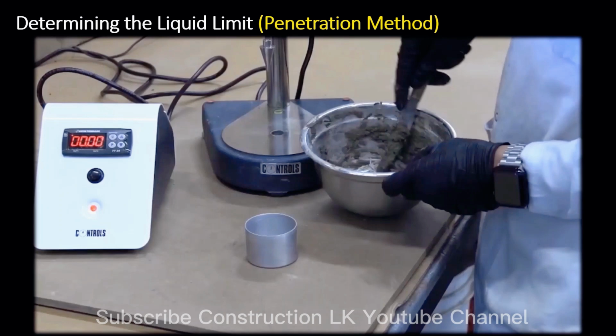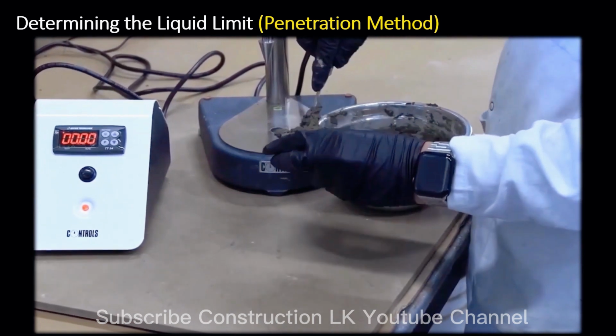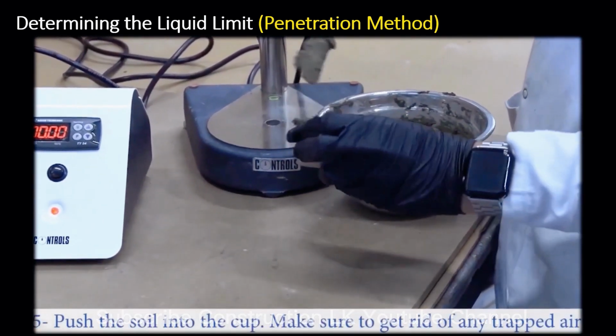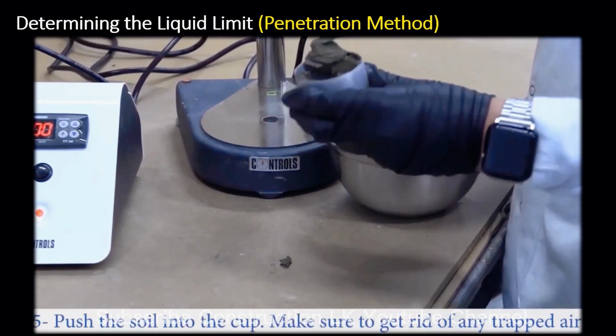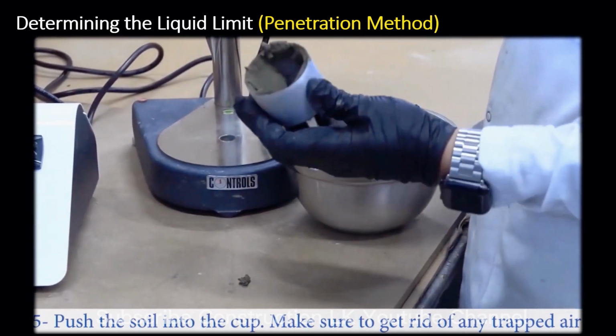The soil to be tested is mixed with water to form a thick homogeneous paste and stored for 24 hours. The paste is then placed in the cylindrical metal cup, which has a 55 mm internal diameter and 40 mm depth.